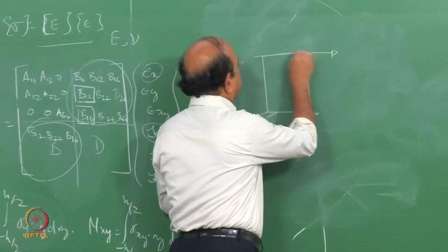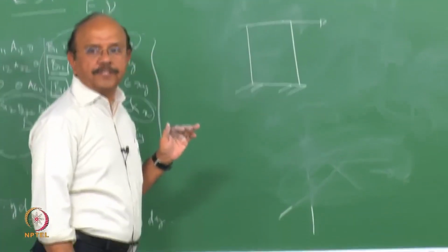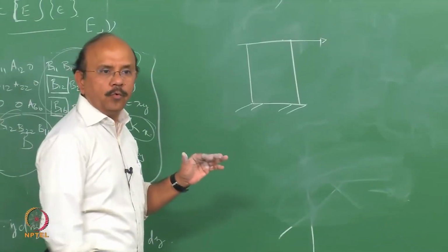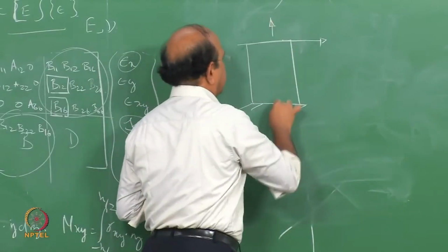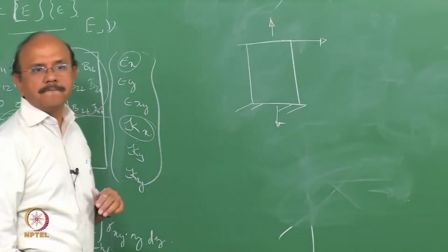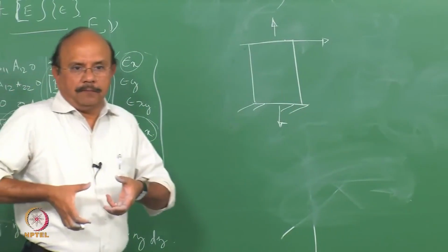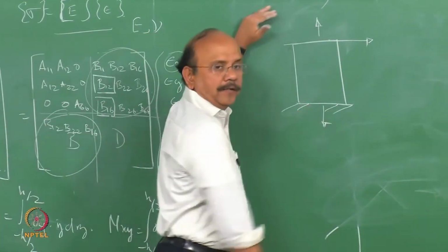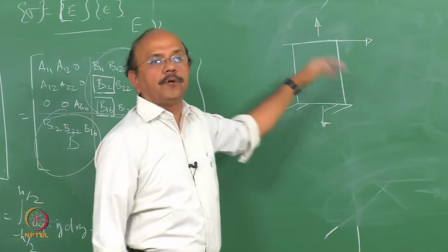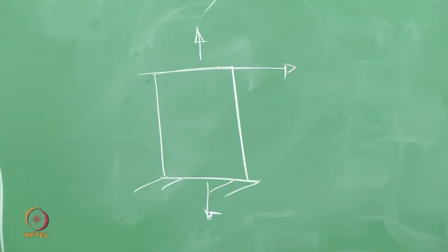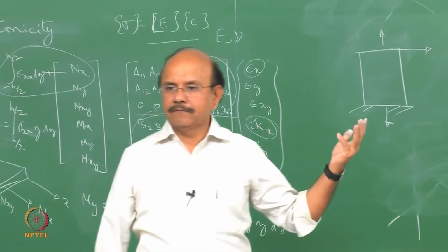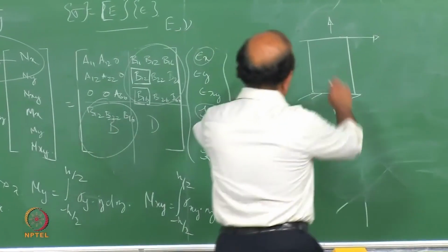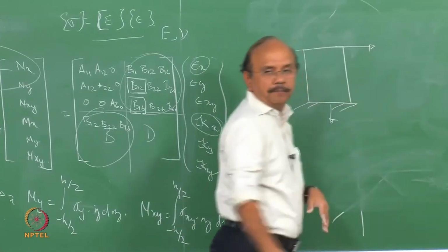One is that both the bottom and the top are fixed not to move in the Z direction. The block is stuck between two platens. This is what happens to a block in the middle of the contact patch. At the edges of the contact patch, one side is free, so I can free it.